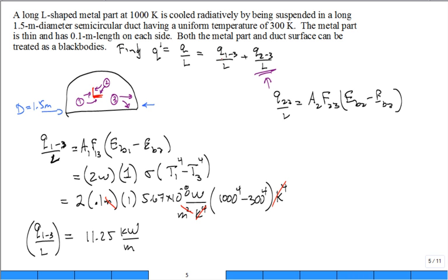Is there any difference in the potential which drives a radiative exchange? The black body emissive fluxes are the same. Is there any difference in the area of 2? No. The difference comes into play because of the view factor. True? The view factor is less, it's lower. So how do I calculate the view factor from 2 to 3?